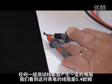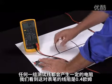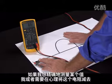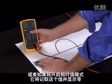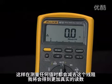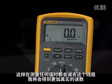Any set of leads is going to have a certain amount of resistance, so I have 0.4 ohms in these leads. If I want to measure something accurately, I either have to mentally subtract that, or if I hit the relative mode, it takes that reading and makes it 0. So now everything I measure will have that subtracted out of it, and I'll get a more true reading.